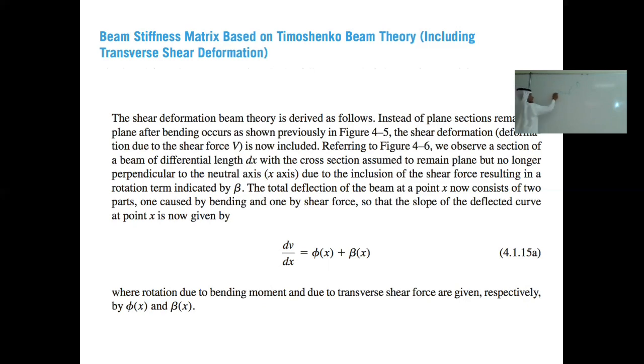Shear. How do you calculate the shear? If you have something here and you have a shear force V, and this is an area, the shear stress will be the shear force divided by the effective area, not the area, because every shape has an effective area. So if you have a circle, a rectangle, or an angle, everything has AS. You will see this in commercial software. It will tell you what your effective area is.